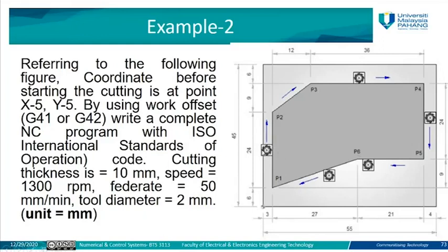And you can see here how the cutter, or the milling tool, goes through the part. The original part, or the workpiece, has the dimensions on the outside here, and inside is the movement of the tool to create this part, which starts from P1 and then returns to P1. The outside dimension for the length is 55, and for the y-axis is 45, and in between you have some positions.